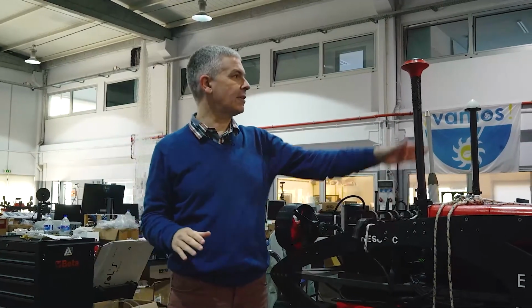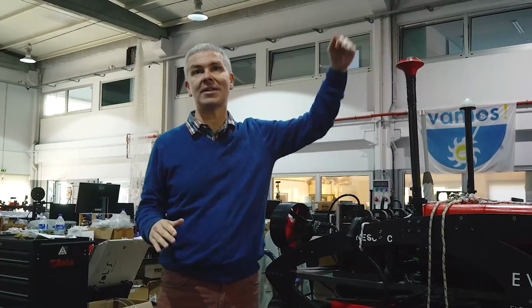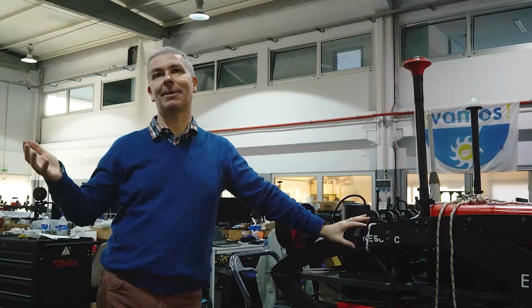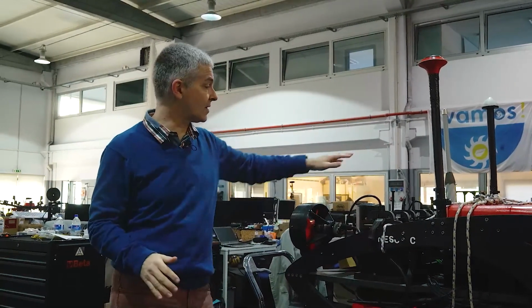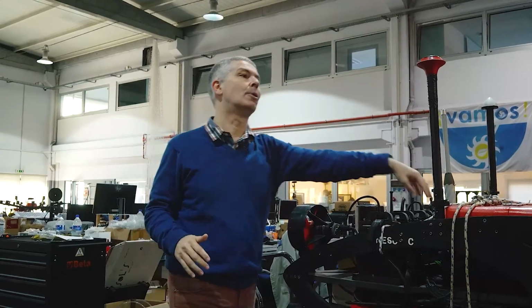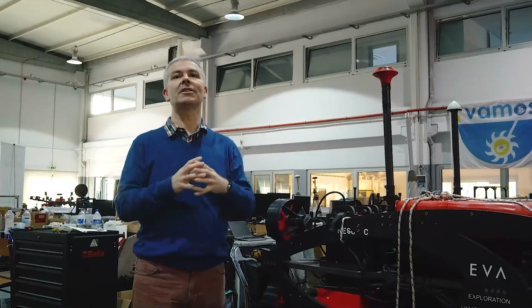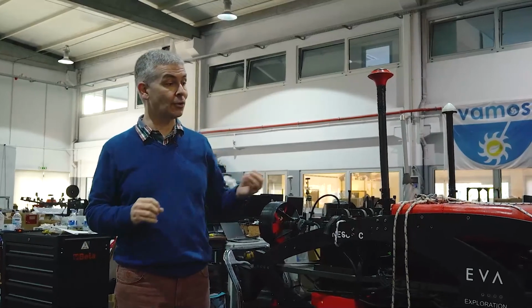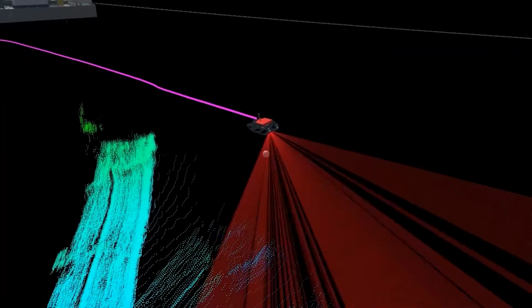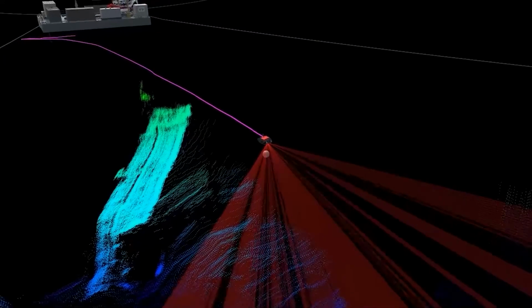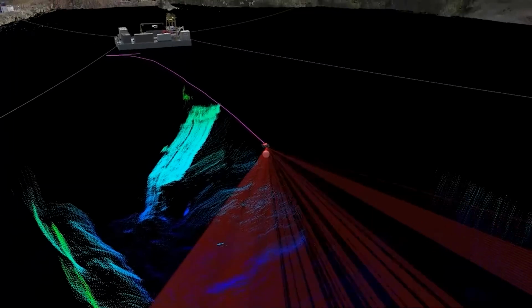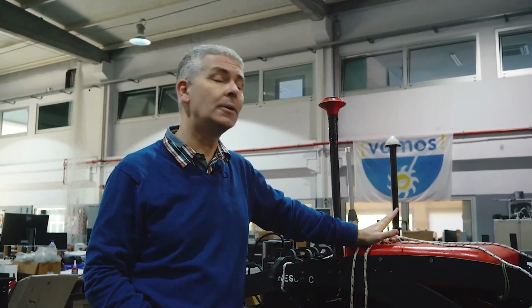When it is at the surface, it uses GPS to know where it is, but once it dives, it must navigate by itself without GPS. For that, it uses acoustic communications. It has onboard high precision inertial navigation systems and fuses all of this information in order to know where it is and also to accurately determine the shape and the profile of the underwater environment to help the mission. This can be done initially in land-based mining scenarios, but it can also be done, and indeed we have done it, undersea.